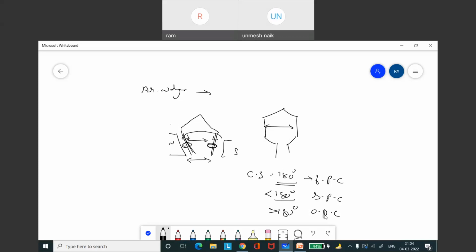The EMF generated in a DC machine is trapezoidal, not sinusoidal, irrespective of the coil span. Whatever the coil span is, long or short, the induced EMF will be the same. If we have a sinusoidal like this, the magnitude varies based on the coil position. But if you see a flat line here or here, the magnitude of the flux is the same.